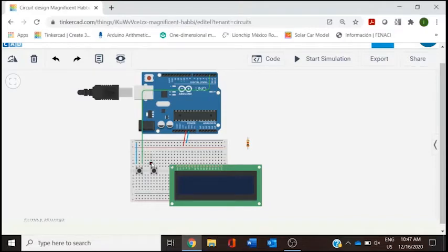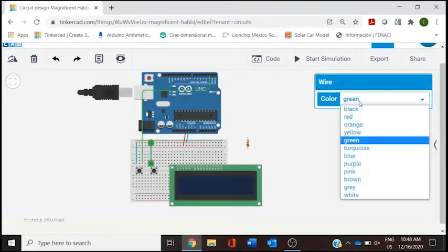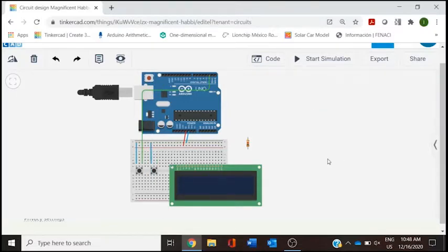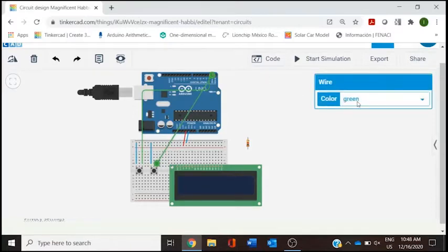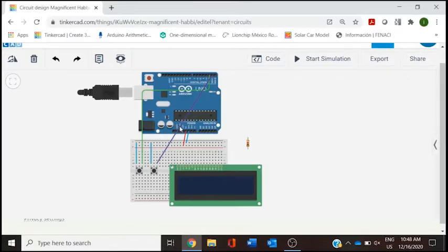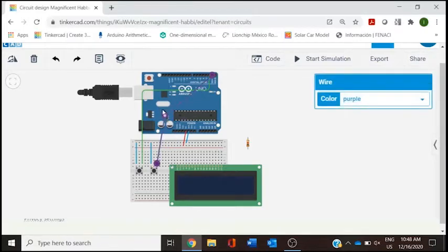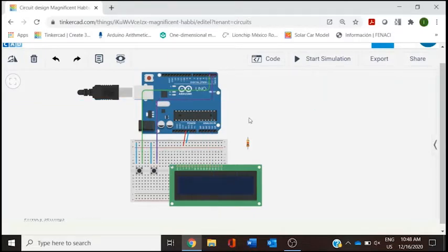The second push button has the same, one connection to ground, and in here, this one goes to blue. The second pin is going to go to our Arduino Uno, and this one is going to be the connection number 1 or digital 1. Changing this color, so we will identify the connections. Clicking for bending the cables.